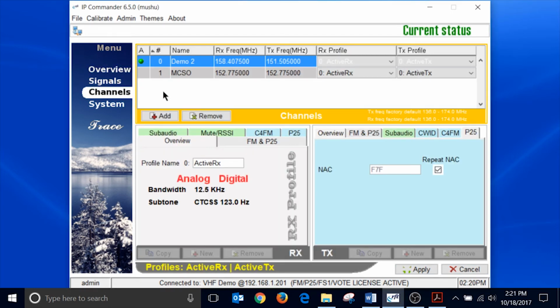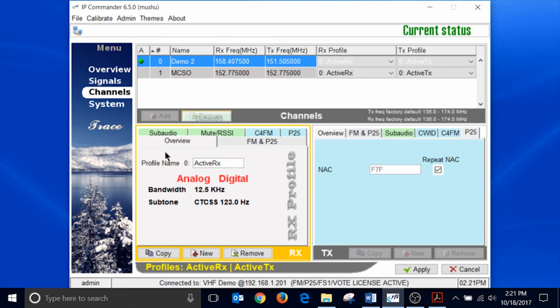Moving on to the Channels tab, the repeater is capable of 256 channels. Currently we have 2 channels, channel 0 and channel 1. Clicking in the name field, you can change the name of the base station. Clicking in the receive frequency, you can change the receive frequency, and the transmit frequency will be done the same way also. The overview screen shows what we're currently set for: analog and digital, 12.5K, CTCSS of 123.0.